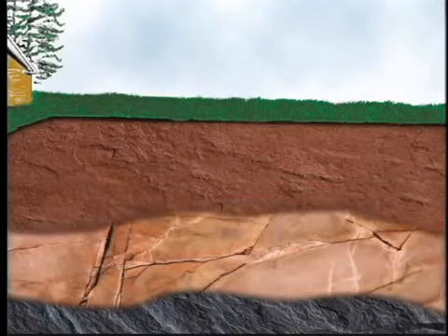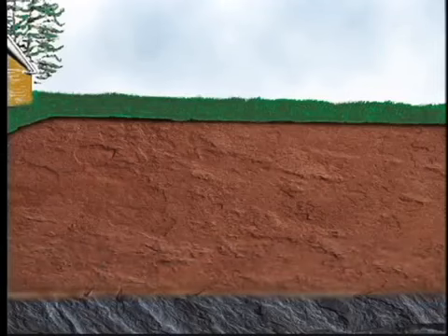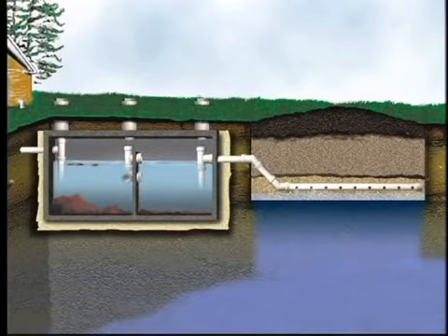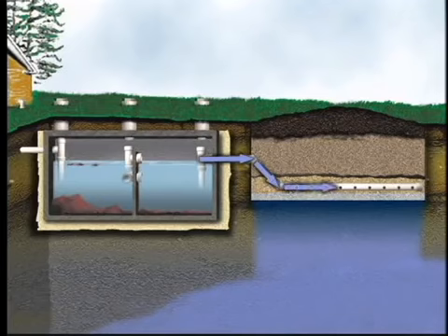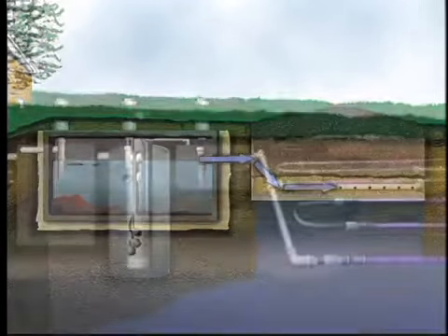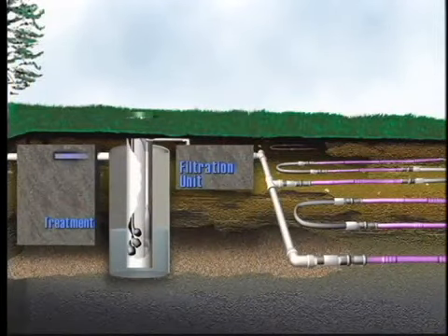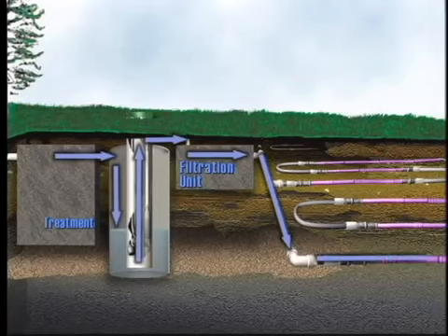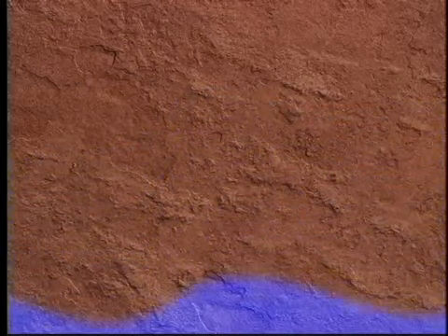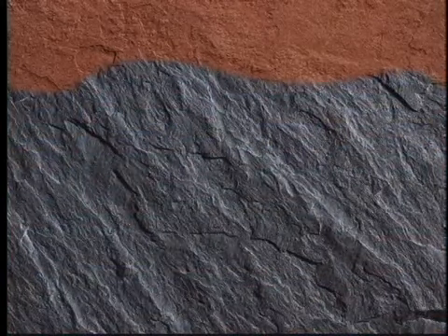There are several options for moving wastewater from your pretreatment system into the soil. The first systems we will discuss use gravity, or the ability of water to flow downhill, to distribute the water throughout the drain field. These systems generally can follow a septic tank pre-treatment device and require good soils at the site. The next systems require a pump for pressurizing the wastewater and distributing it throughout the drain field. The pressurized systems are used in areas with limited soil depth available for wastewater treatment. This type of shallow soil can be in areas with seasonally high groundwater or bedrock near the soil surface.